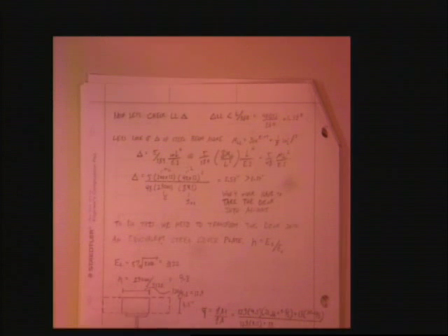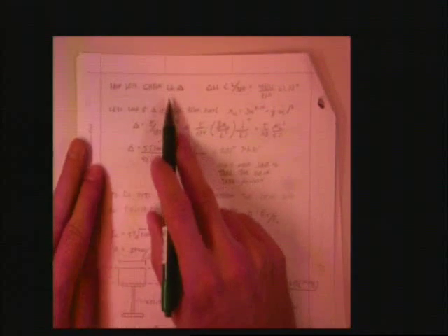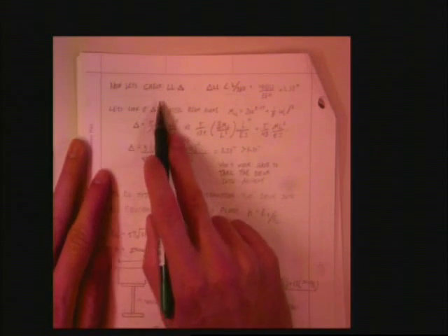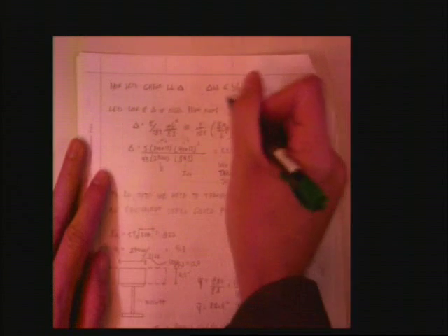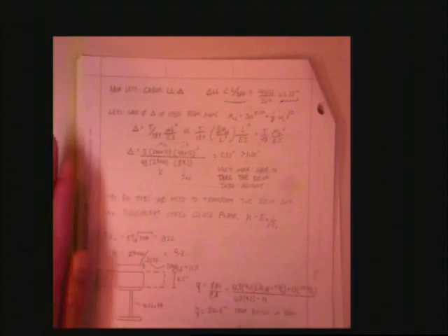Awesome. So now let's work the problem the other way. Oh, no, I take that back. I guess I'm going to do live load deflection checks first, because it's not totally straightforward in how to do that with these things. You should know how to do it, but you probably haven't done it in a while. So we're going to hold L over 360 as our live load deflection limit. We're going to find 1.33 inches as that limit.